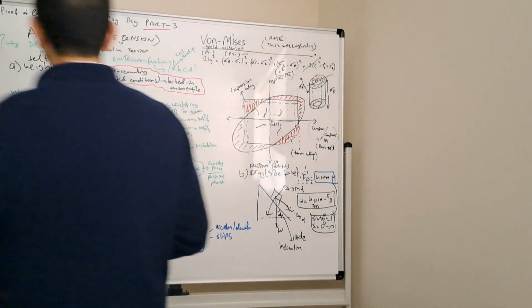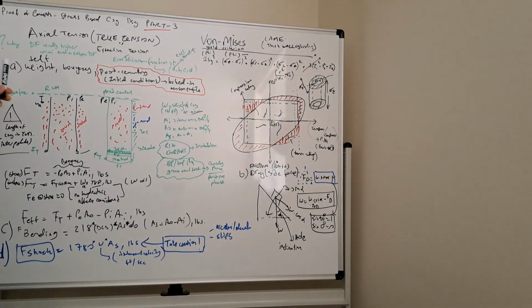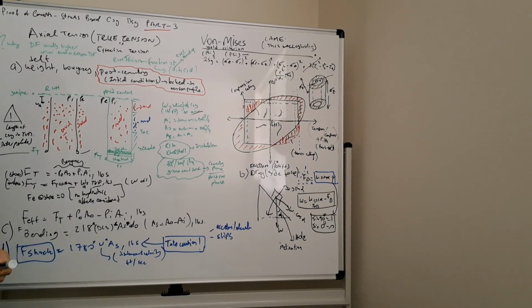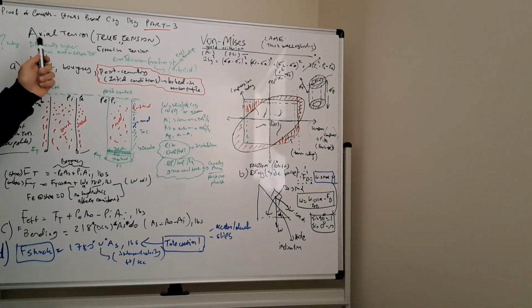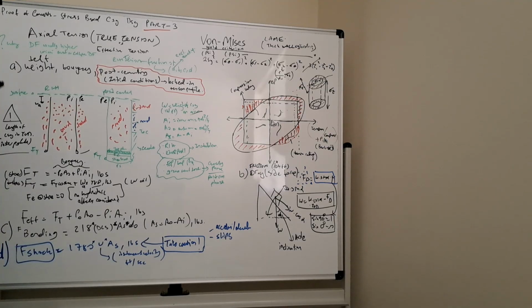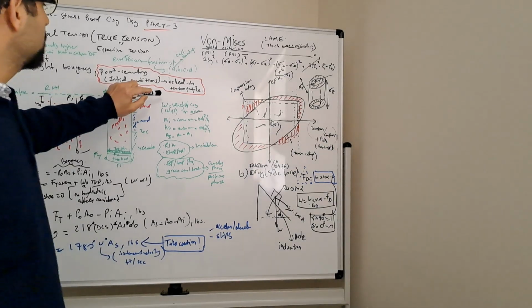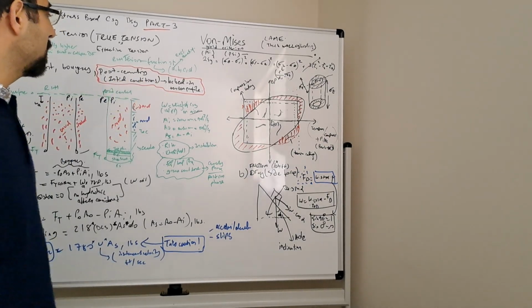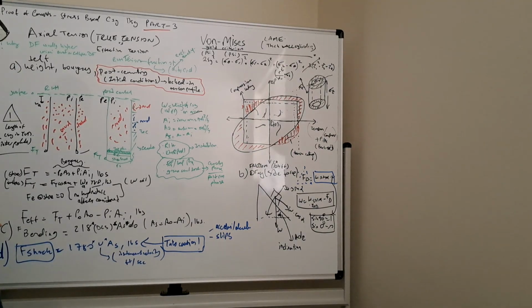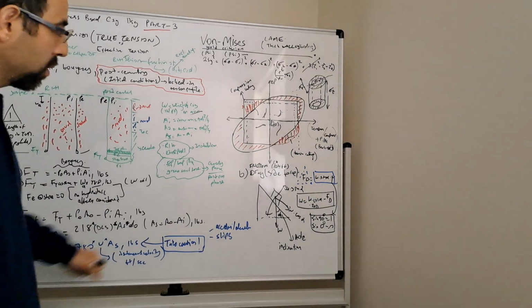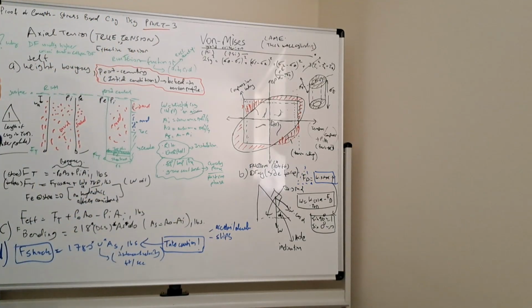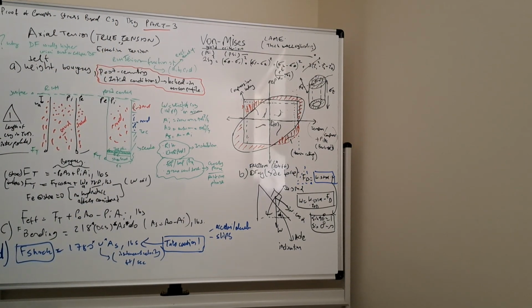Okay, so let's move into the major elements. First, I put a question mark here. What is the reason that the design factor is usually higher for tension than for uniaxial burst or collapse design factors? We are going to try to answer this on the second page. The first element that I'm going to talk about is self-weight, buoyancy, and then the post-cemented tension profile, and then I will cover the bending, the shock load, and the friction in a deviated hole.